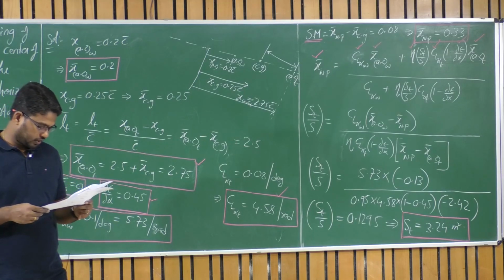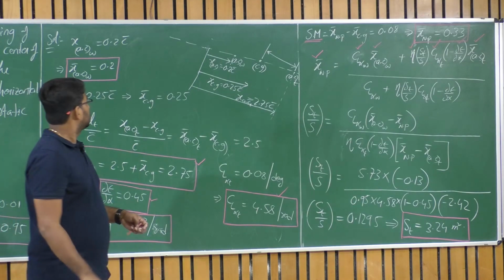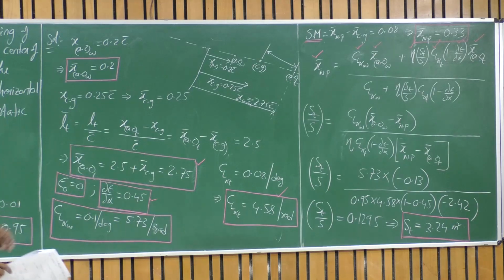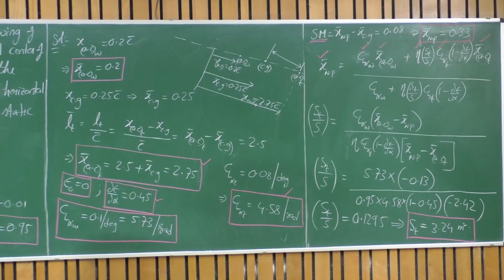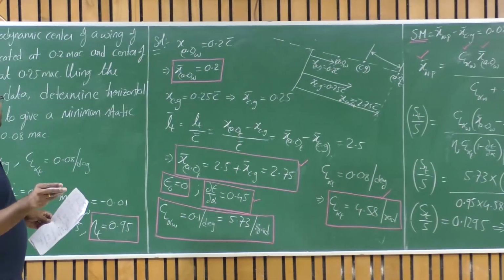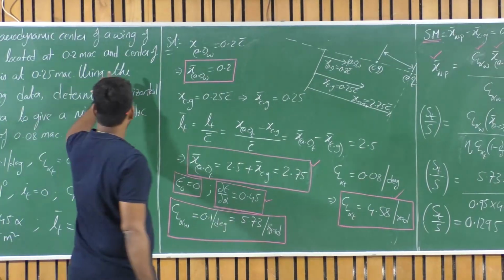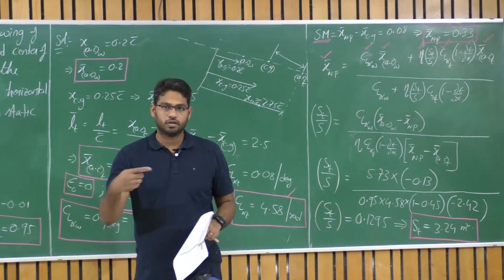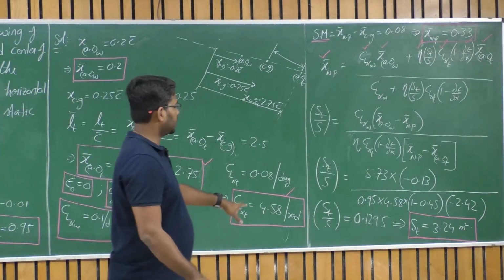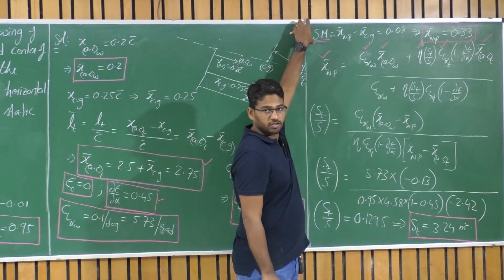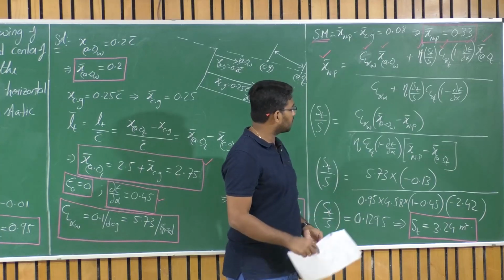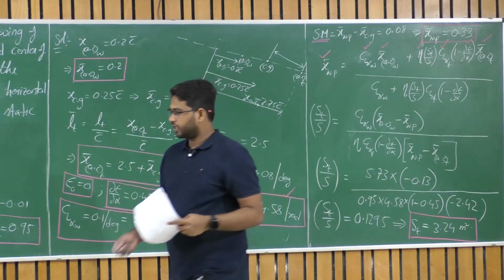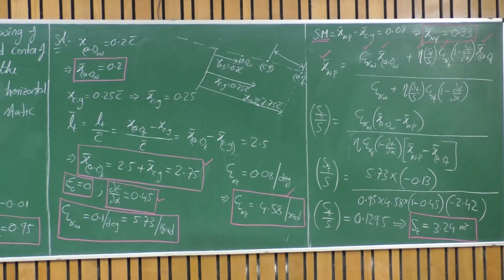Okay, that's a wing area we need to figure out. So from the given data we are able to find it out. Yeah, sorry, that's a tail area. So given the wing area, we are able to figure out what is the tail area. What should be the percentage of tail area in order to have this static margin? So what will be the tail volume ratio? Can we find the tail volume ratio of this?